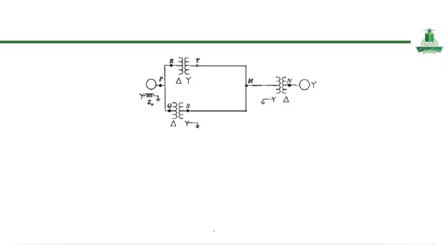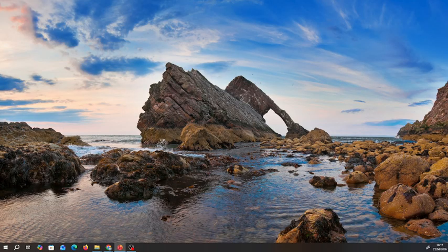The transformer connections play a crucial role in determining whether a zero sequence current can pass through the system, as delta windings can block or circulate these currents internally, while grounded WYE connections, star-delta connections, provide a path to ground. So let me just go to the animation.